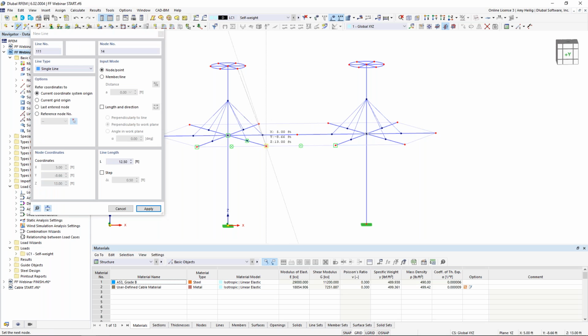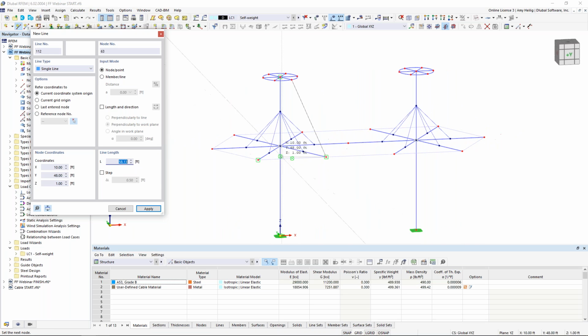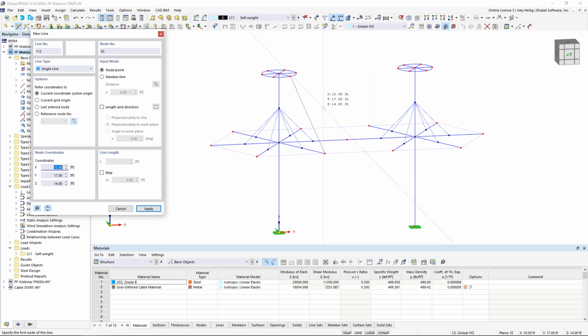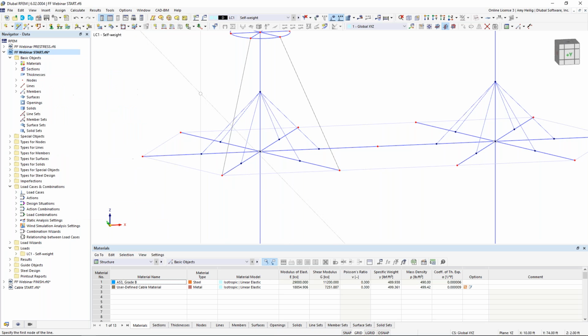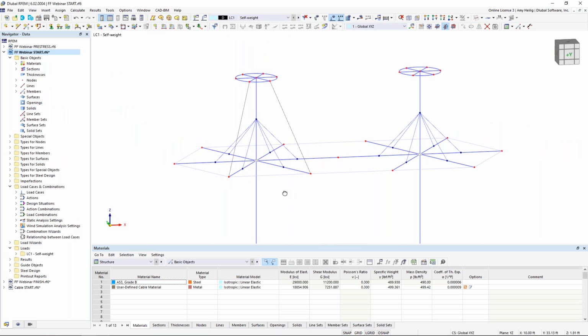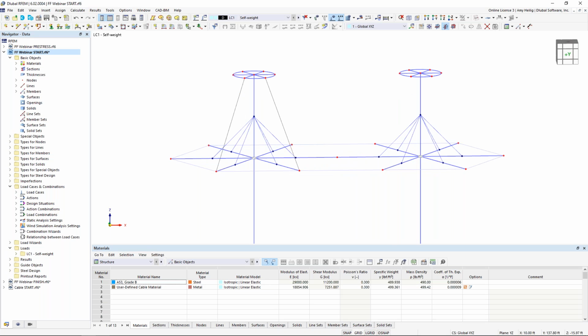And it's going to be used to further define the boundary lines here of my first fabric surface. So I'm just snapping from the top of the model down to the bottom, and I right-click a couple times to exit out of this option. To create a new fabric membrane, we need to generate a surface. And the problem with these surface options available here is that these must all be in one plane if we use the surface options available.